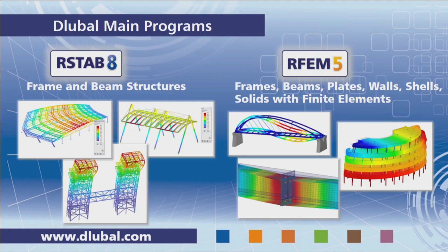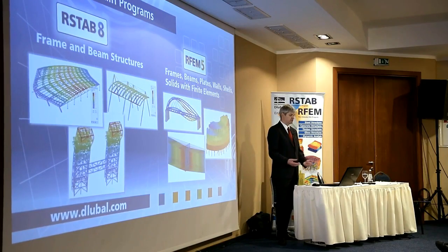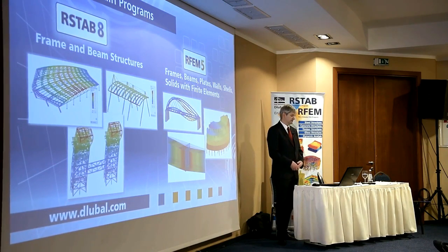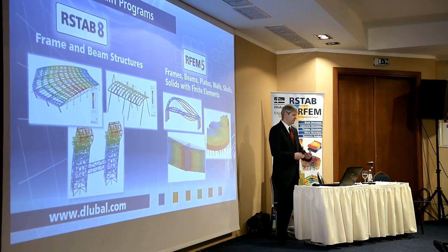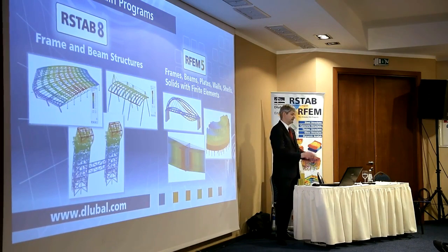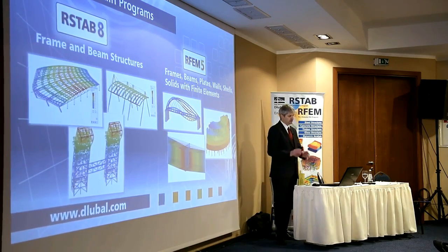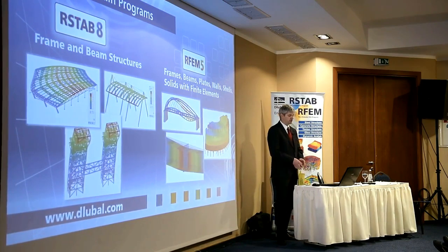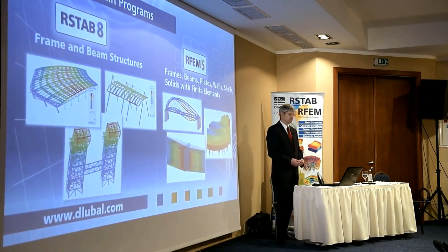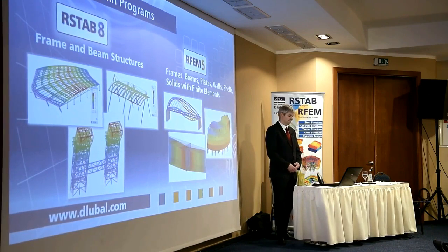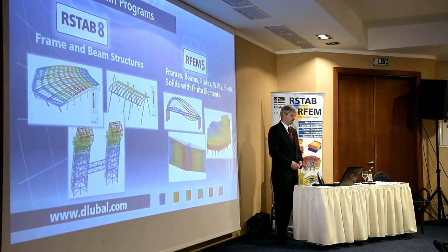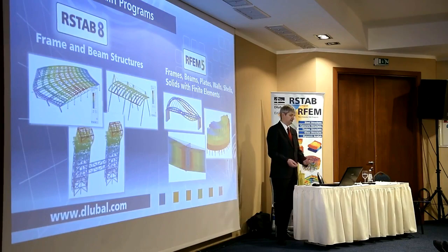Over time, this came, and now we have both software, so you could call it the more simplified version dedicated to beam structures would be RSTAB, and RFEM is the more general structure that can handle also slabs, walls, solids, and of course also beam and column elements or frame elements. So if you want the full solution, you go for RFEM. If you can say, I only need it for frameworks, you could go for RSTAB.